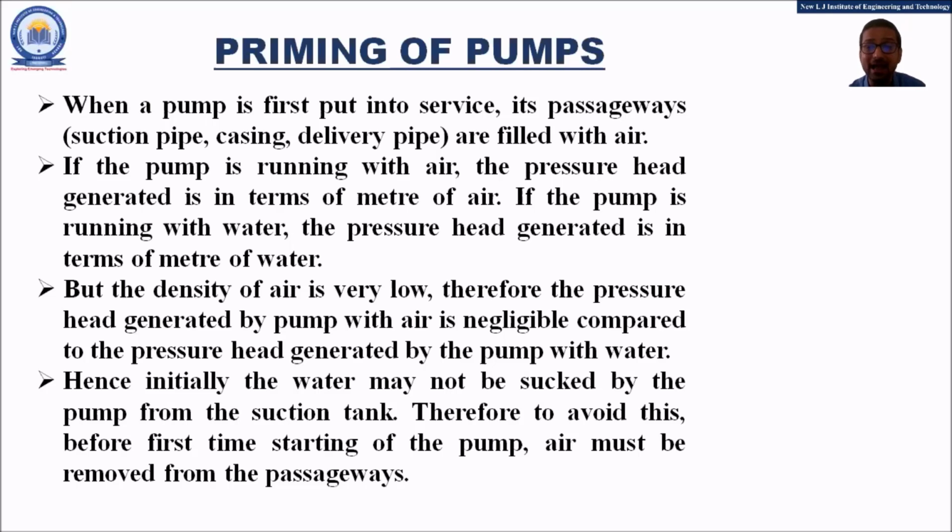So in order to avoid this drawback, before starting the pump, the air must compulsorily be removed from the passageways. If the air is not removed, then the pump will be sucking the air because of its lesser density, and we will get no liquid at the outlet.